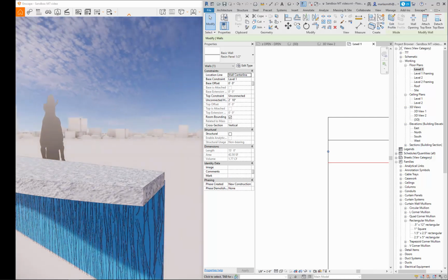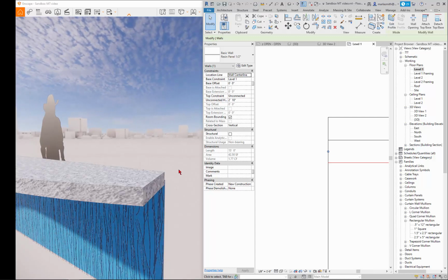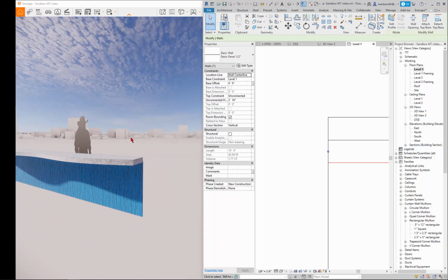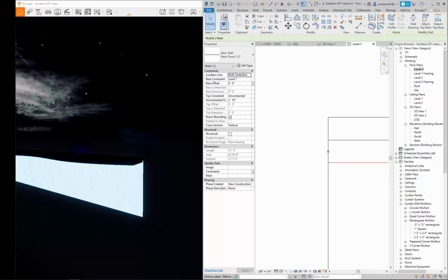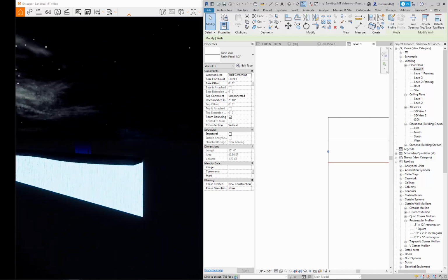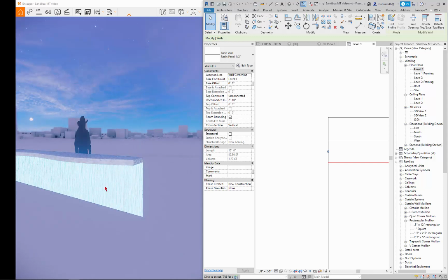If you get the light right, the roughness shows up. The other thing you can do is with the self-illumination, I'm holding down the shift key and pressing my right mouse button, but if I go to the night, then you'll see that guy start to glow. You'll get a nice glow with that. So you can start to play with that. When we come back, I'll show you how to do an even recessed lighting glow.